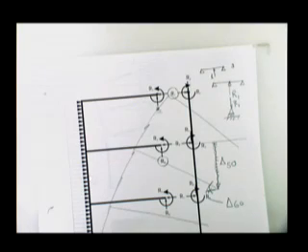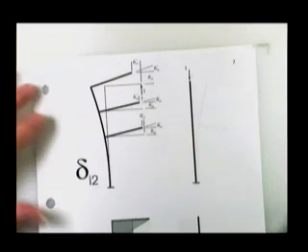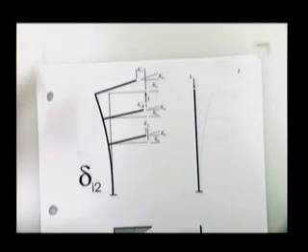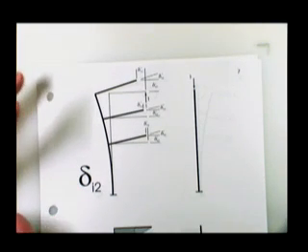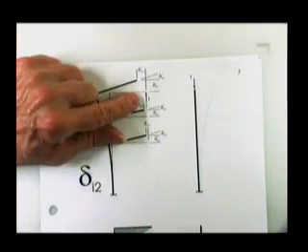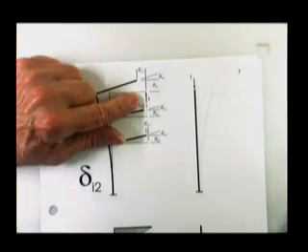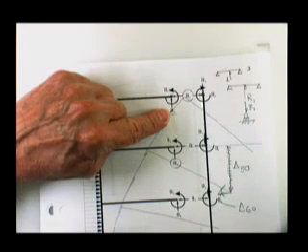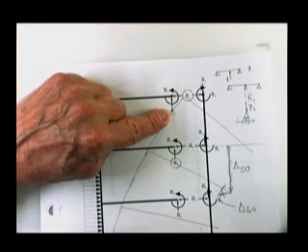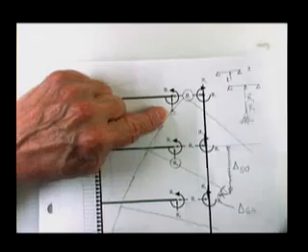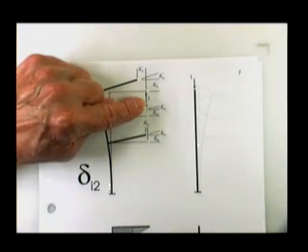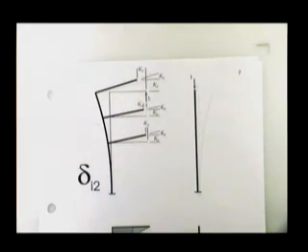You can guess any direction you want, but when you do that, your ones have to agree with that. And the other side of that coin is a lot of people say, no, I put the ones on here, and that's what set this guy's arrowhead. But I don't care who came first, the chicken or the egg, but these arrowheads here have to agree with your unit load guess arrowheads. That's got to happen.